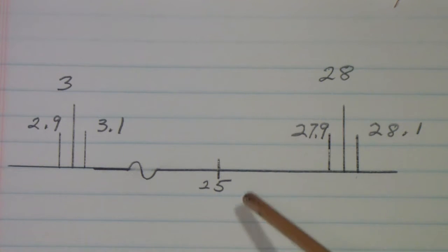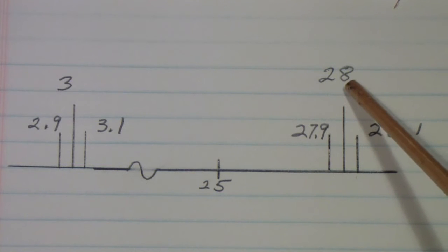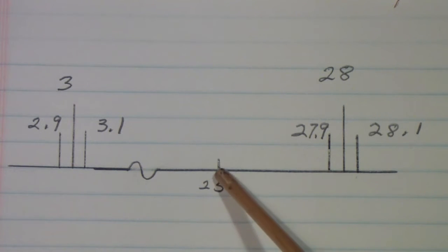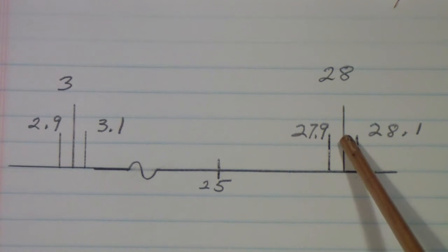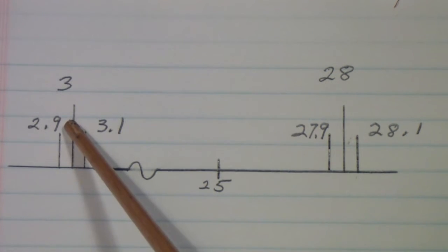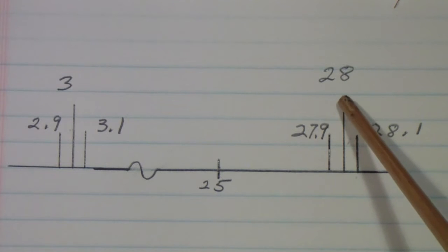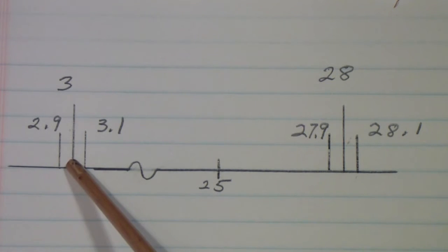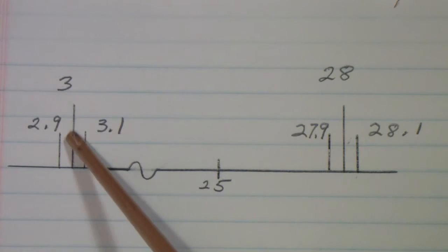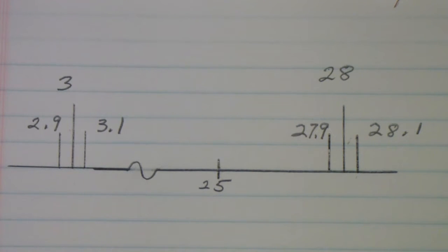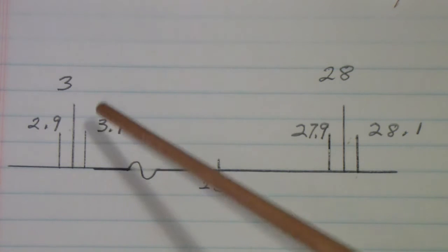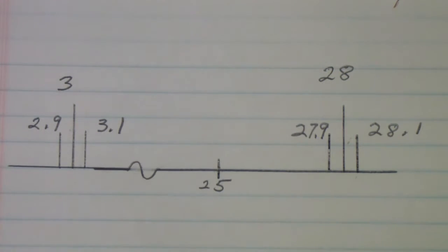The idea is, if I mix that 28 megahertz signal with a 25 megahertz local oscillator, it will in effect move the 28 megahertz down to 3 megahertz. That is the difference between 28 and 25. 3, of course, is well within the range of the Analog Discovery. In fact, 28 would be as well.